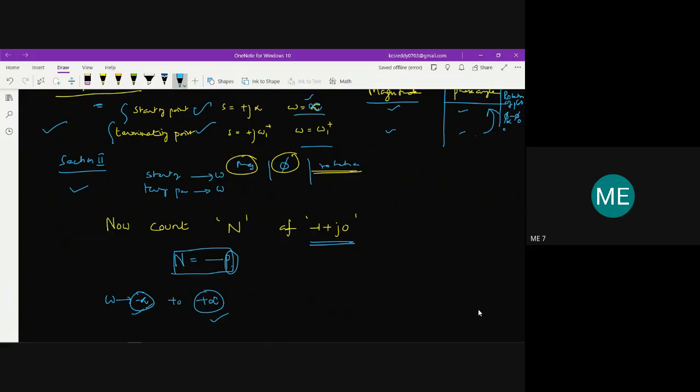If I substitute the magnitude, it will become 0 for both cases. So the 2 points coincide at the origin, because the magnitudes of these points become 0. So there exists some rotation about the origin with r tending to 0 before the plot terminates at the origin. These rotations will not affect the encirclements of minus 1 plus j0.